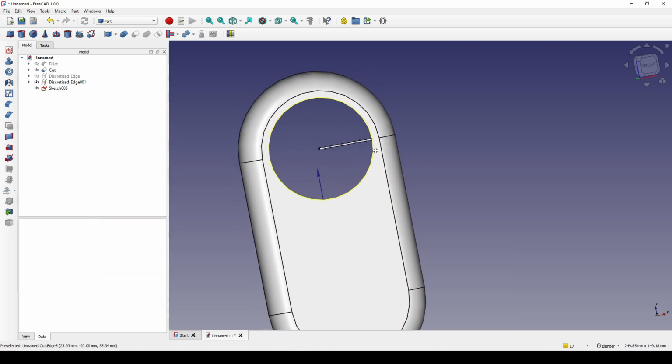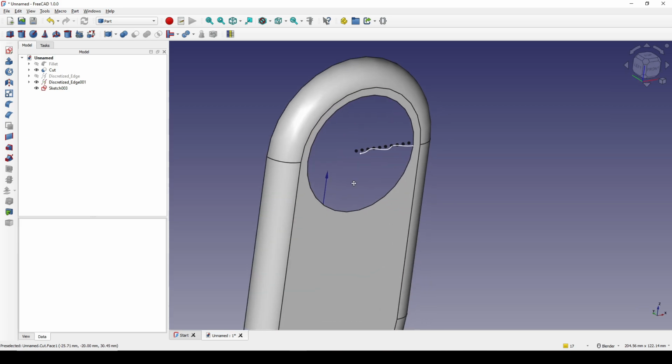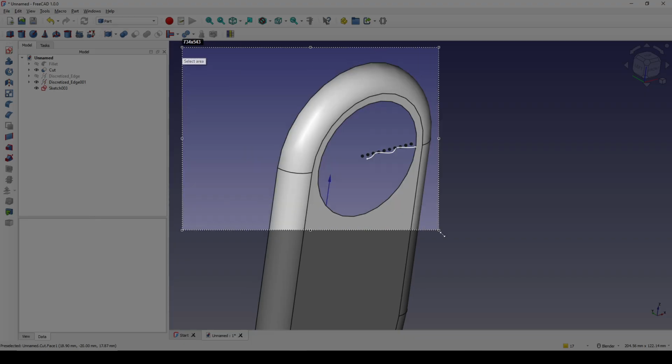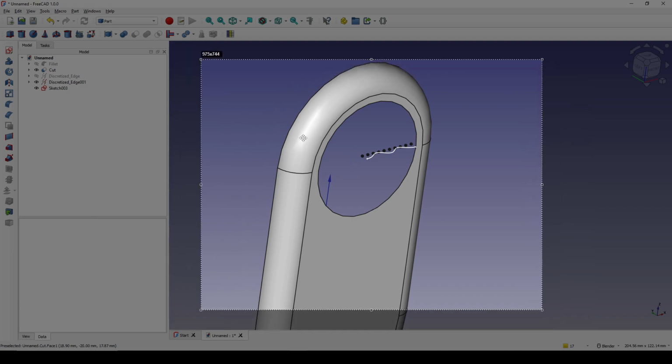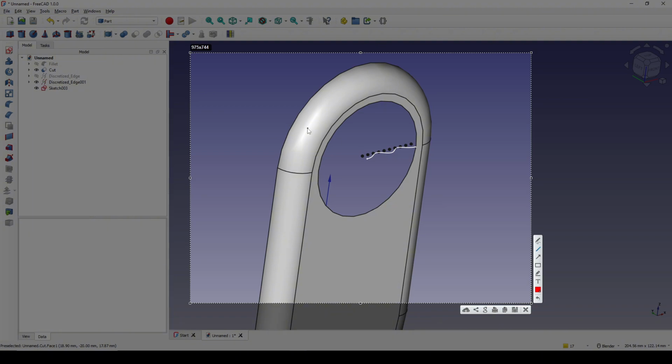And I come back to my original curve. I want to revolve this one around one axis, so I need a line, like this, and I will revolve this curve around this axis. And if the surface offsets to the wrong direction, I just simply go back to the revolve and revolve this one back in the reverse direction, and it will fix the problem.